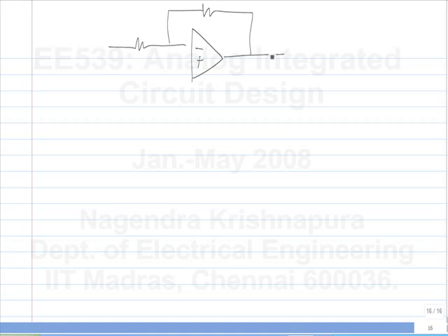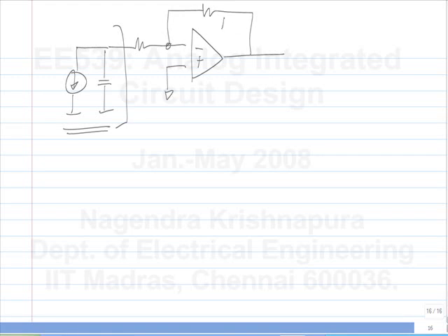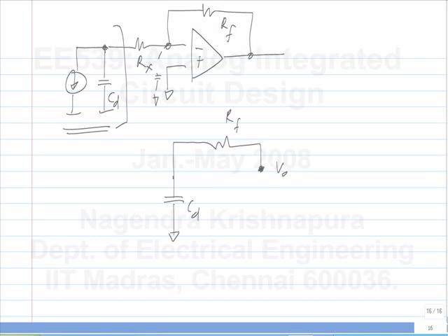So here you introduce a resistance between the photodiode, between the diode and the op amp. Okay. The idea is still the same. Before, if the capacitance was here, okay, so the phase shift at high frequencies of the feedback network was minus 90 degrees. Okay. So before the circuit looked like this, right? So the phase shift from here, V out, to the op amp input is minus 90 degrees. What is it in this case?